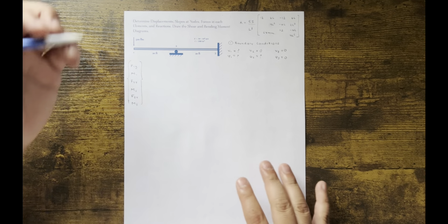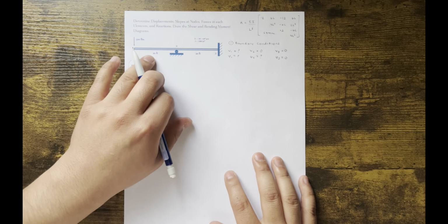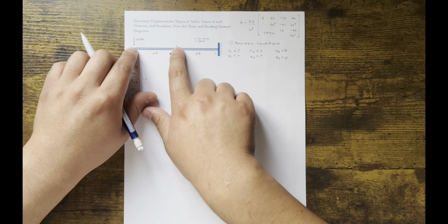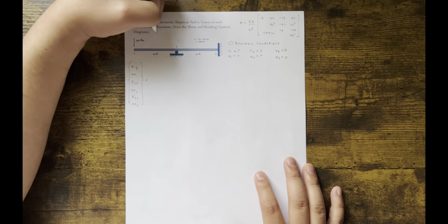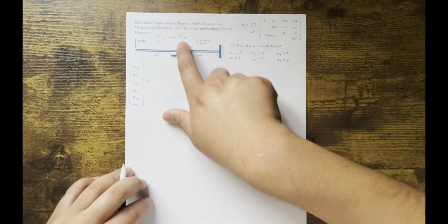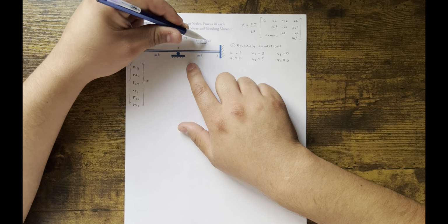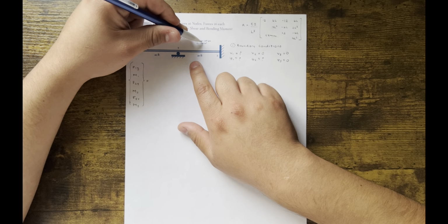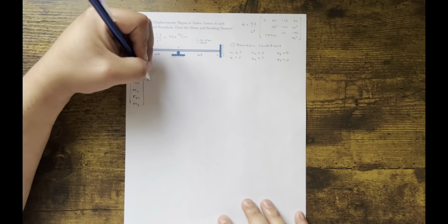This is step 2, global equation. In this case, EI over L cubed. L is 20 feet, so from 1 to 2, then from 2 to 3, it's the same length. That's how we're discretizing our system. In this case, EI over L cubed is going to be 434 pounds per inch. That's a stiffness. You get that just from EI, which is given as 30 times 10 to the 6, I is 200 inches to the 4th, and L is 240 inches. Don't use 20 feet. And that's how you'll get 434.